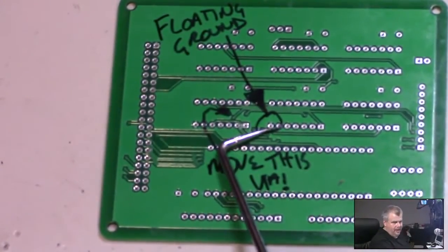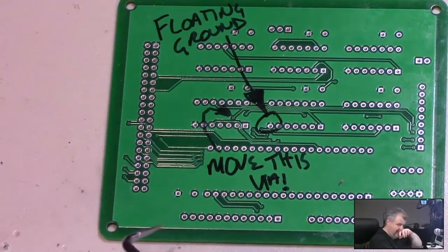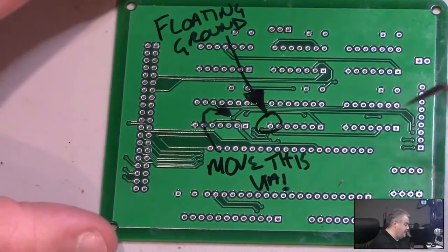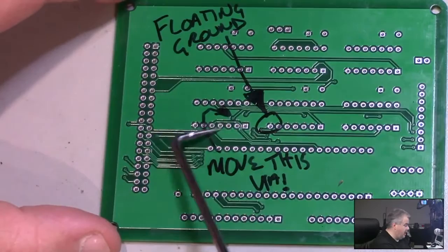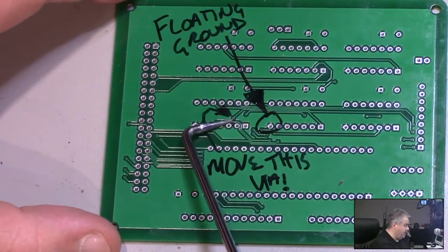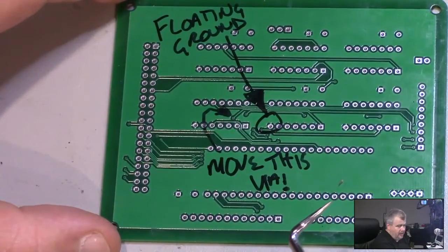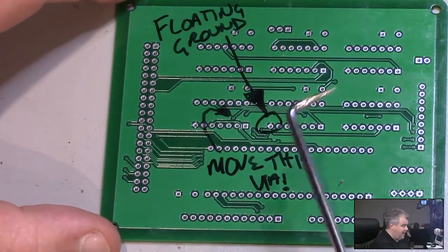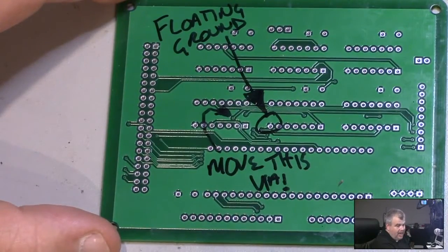All right. So if you look carefully, you'll see this thermal relief business here, right? But this ground plane is connecting to this pad, right? As it should be. But the difficulty is that because of all the vias that I had to do on this, and because I wasn't paying close attention, basically these two vias, especially this one, and this selection of vias down here, made this piece of ground plane an island, right?